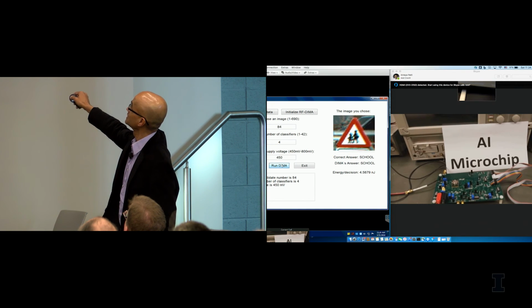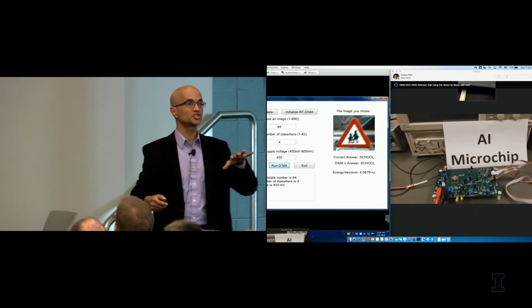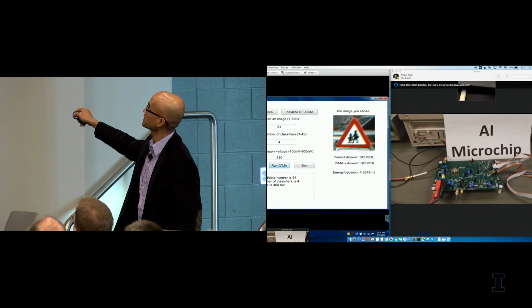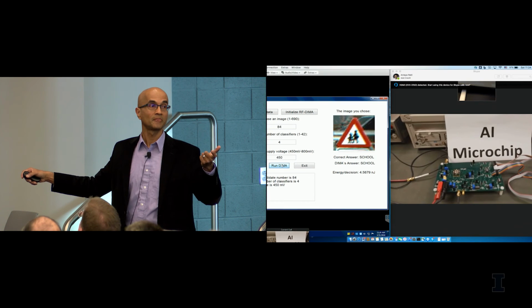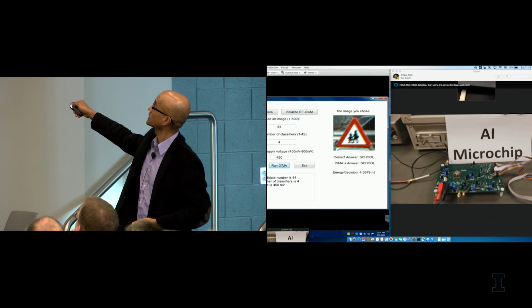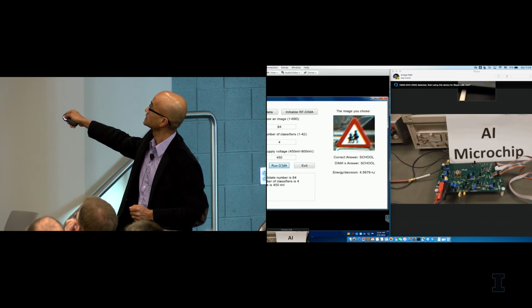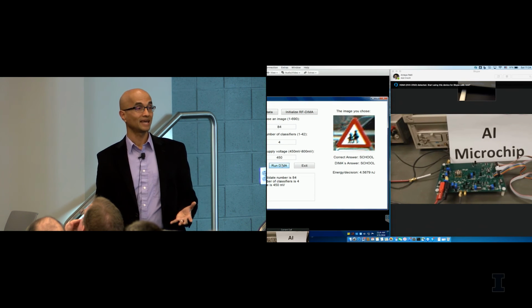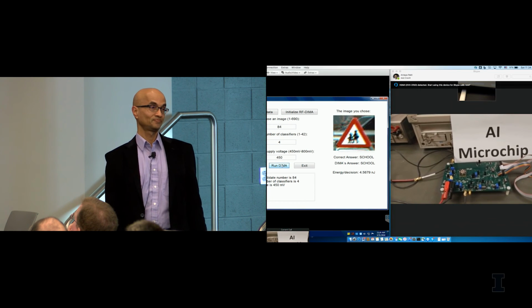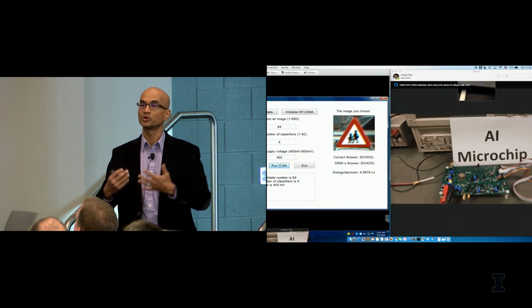CBLP is actually making decisions. So the computation is occurring on this strip, and then it's converted into digital. Remember I said we compute in analog. That's what makes it stochastic. And then the ADC produces the decision at the output, and then we look at it on the computer. So computation is this part, the memory is this part. In typical AI systems, your memory will be gigantic and computation will be a small strip. So that's why we have to optimize this interface between memory and computation.